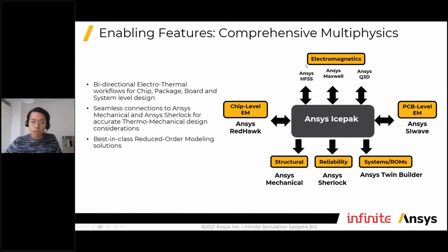It also consumes the thermal losses, or we say the electric losses, ohmic loss for instance, from different electromagnetic simulation tools in Ansys, putting it into iSpec. Of course, if you are doing different electromagnetic simulation, a third-party one can also be properly prepared and then put into iSpec for mapping the loss on your traces and on your systems.